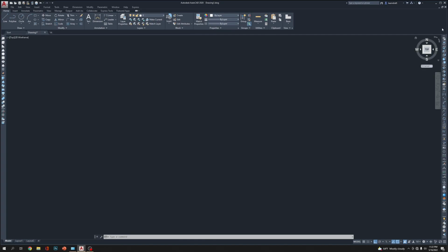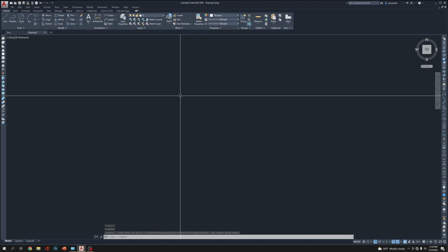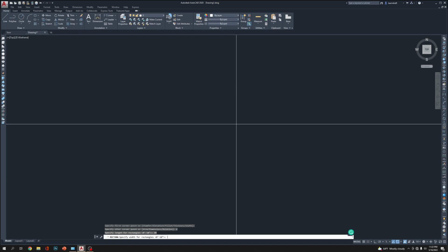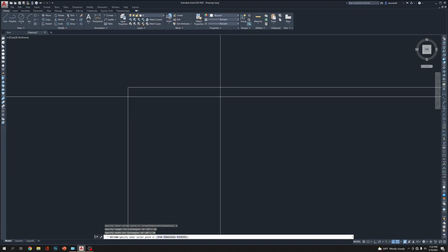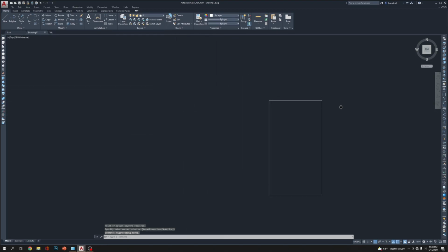Go to the top view and draw the plan first. So this plan is going to be like this. Let's see, enter, click D, enter, and let's say the desk is 20 by 36 inches. Click, enter, click. Okay, so I'm going to keep it here.